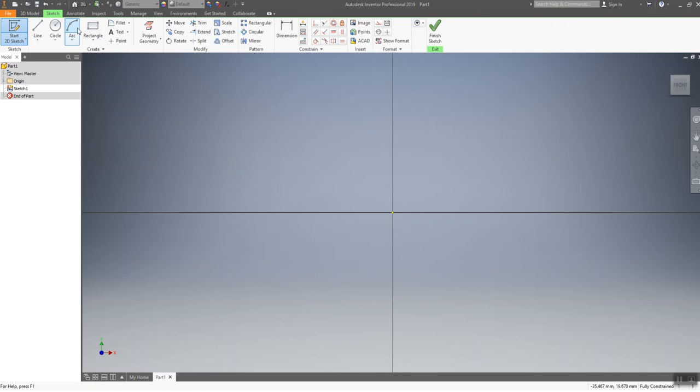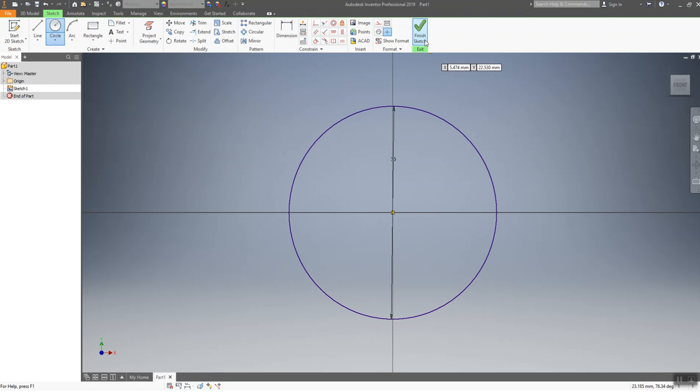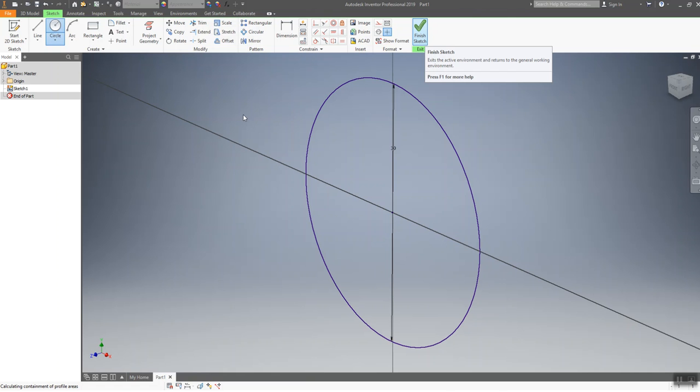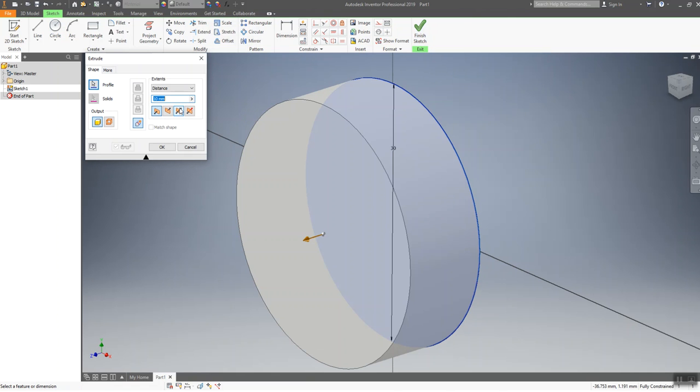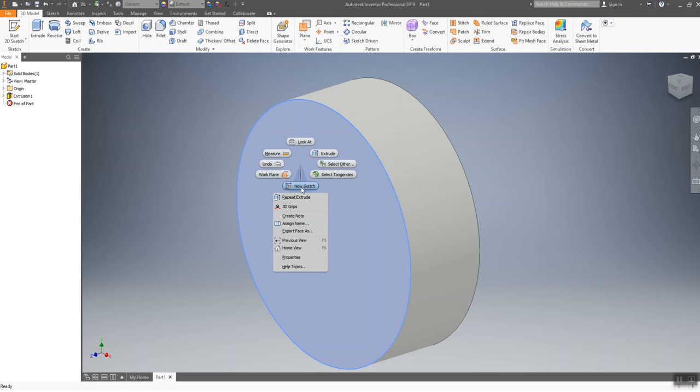The first is that if you are creating something like, let's say, a circle, we'll make it 30 millimeters in diameter. So when I've made this circle and I've extruded it and given it depth, anytime I create a design on top of that, I need to be careful that I'm not just creating lines on the face here, because lines, as I've mentioned before, don't show up on our 3D printer.